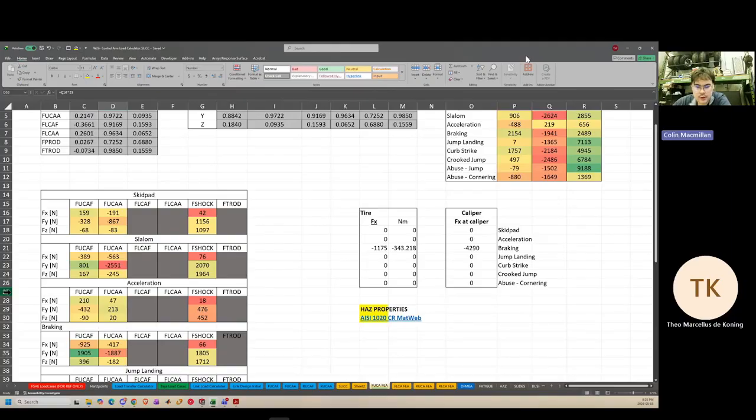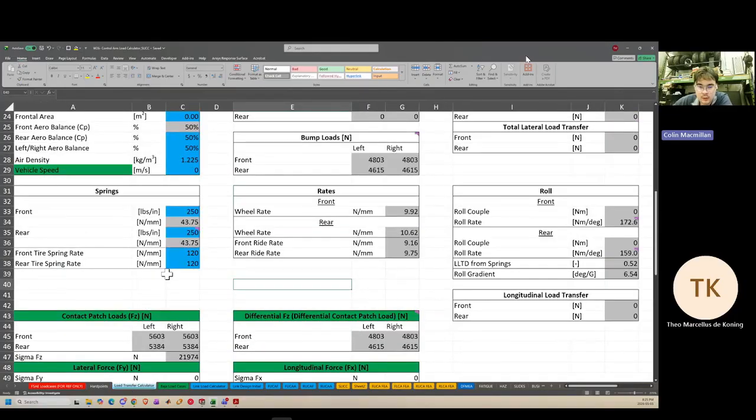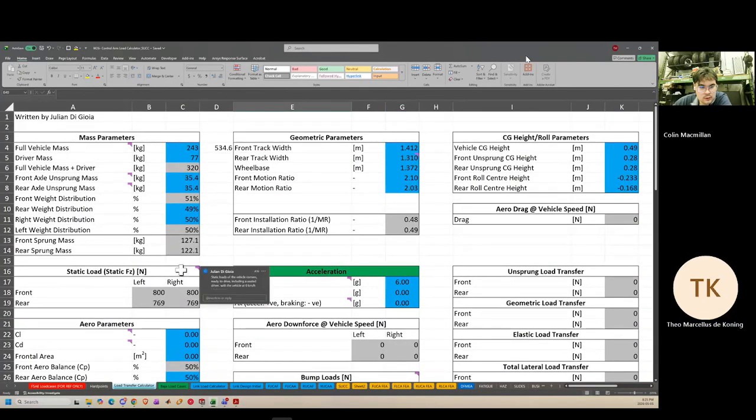And then one other thing I'm a little confused on is how did you get the IMU data, the accelerations, into the forces, the contact patch force? Can you just repeat it one more time? It's just a load transfer calculator that uses weight distributions and vehicle geometry. Okay, got it. And then you assumed that the weight distribution between the front and the rear was 50-50?